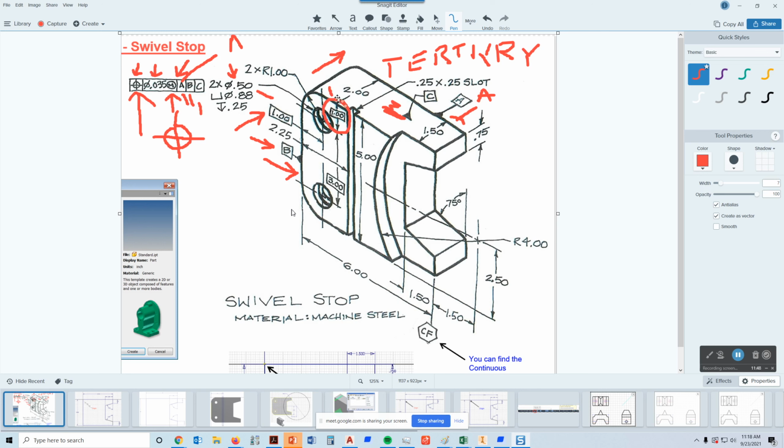It's this 1 right here that's also inside a box. So that's called a basic dimension. Basic dimensions are considered to be perfect dimensions. There's no tolerance on it. So we know we can't build anything perfectly, but what we're saying here is that if we could perfectly locate a tolerance zone, and if the tolerance zone had a diameter of 0.035 and was a very small cylinder, and that cylinder were perpendicular to A, and if the center of the circle were located perfectly 1 inch in from B and 1 inch down from C, that would be the true position for our hole.